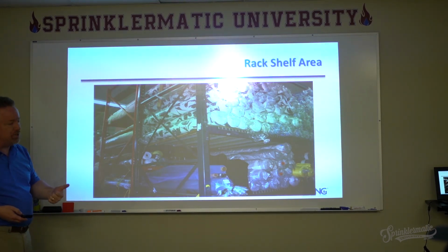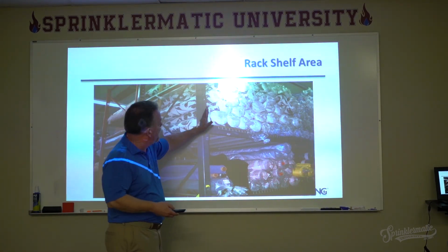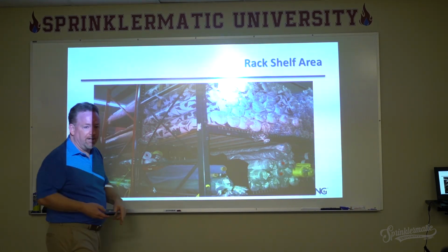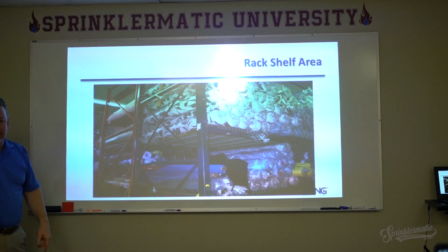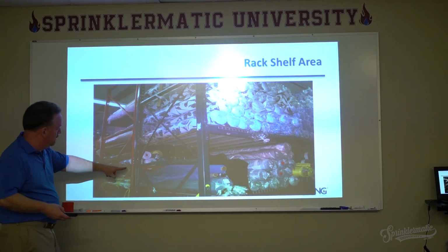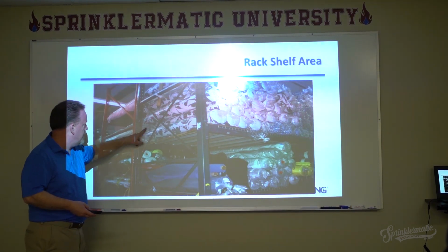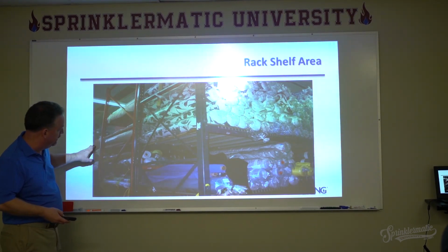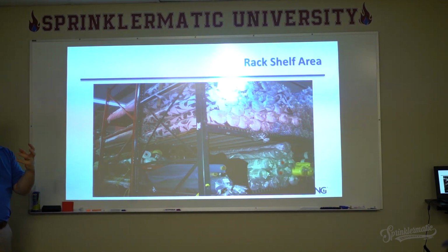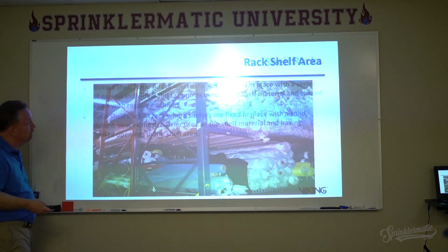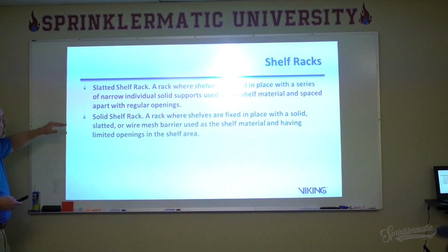They've taken an open rack construction. They've loaded it all the way out to the vertical barrier, the vertical supports, killed all of the whatever flue space was there. There wasn't much there anyway. They ran it right to the back here. Now this is a new set over here. All right. They jammed it all together. What have they done? They just created an entire mass of material that has overrun the shelf area. No flue spaces at all. Big problem.